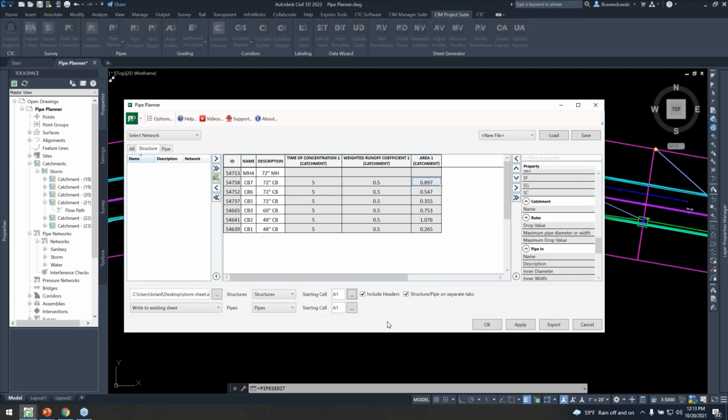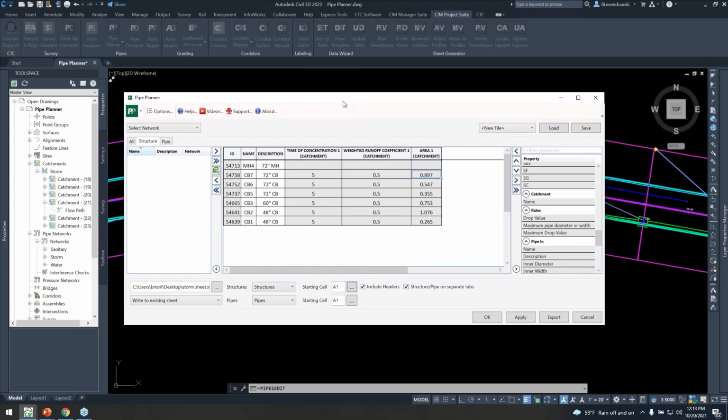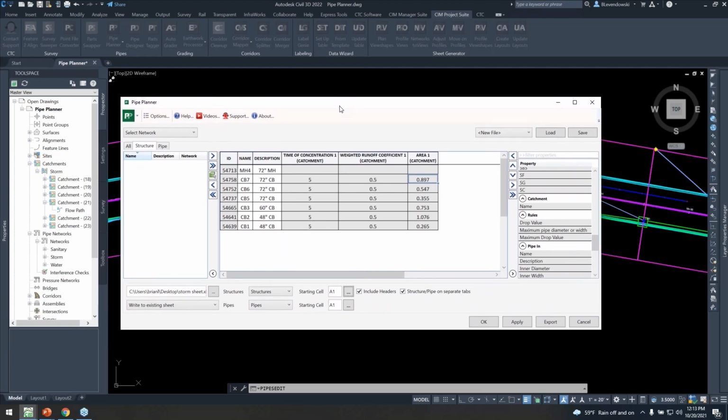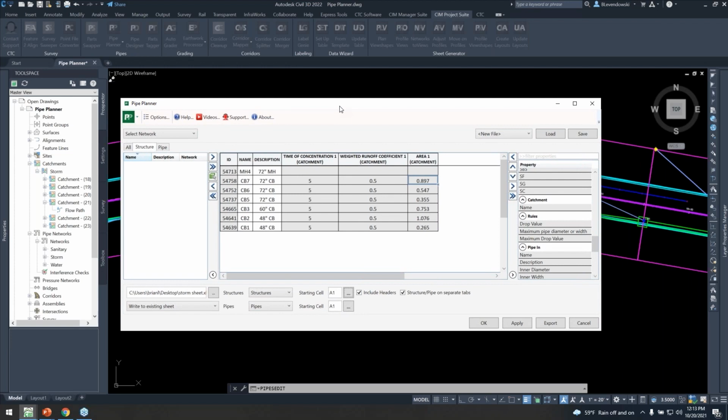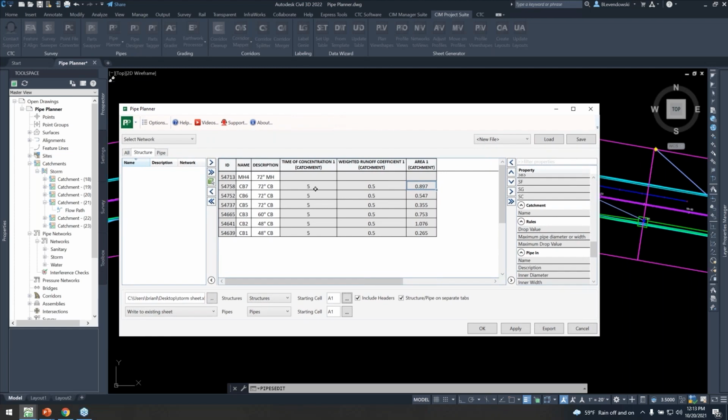If you've seen Pipe Planner before today, you've seen some of the other workflows I've used it for, many different things. Pipe depth reports, manhole schedules, any kind of reporting you might need to do. It's a very, I want to call it open source. It's a very open platform tool. Choose your parts, choose your properties, assemble the table any way you want, and then do with that what you will, either editing those properties and writing back to the drawing by hitting the apply button or going out to Excel with it.